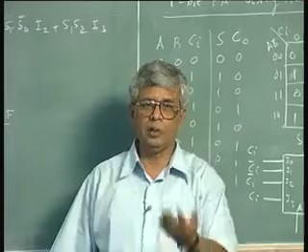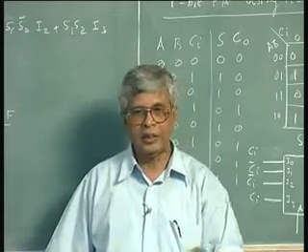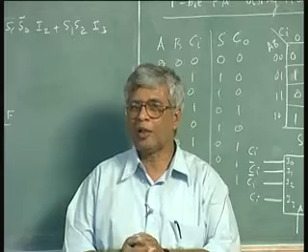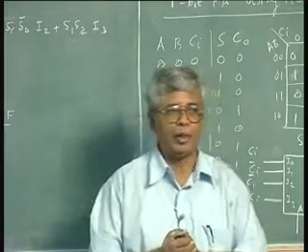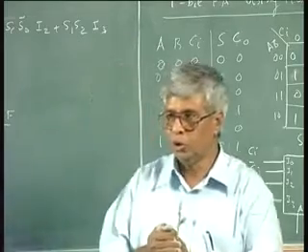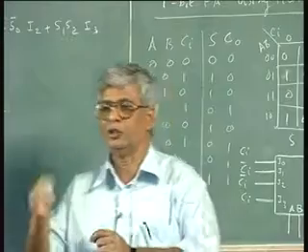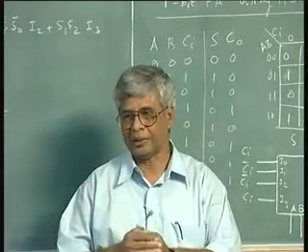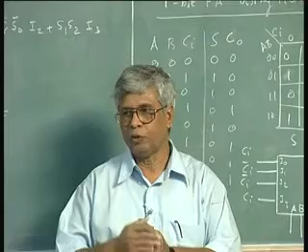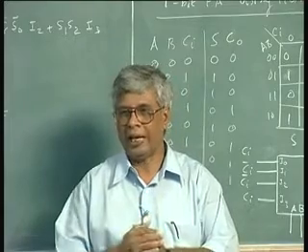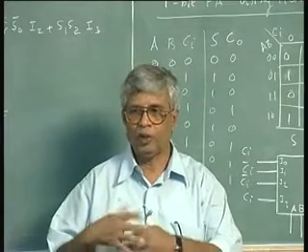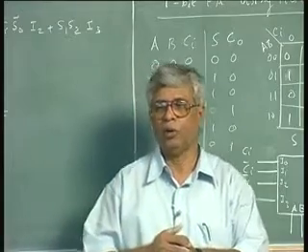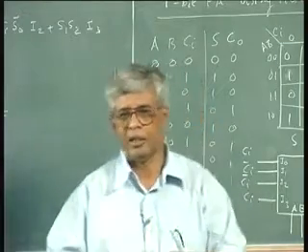So there is no need for me to give you separate homework. What you can do is take any 3-variable Karnaugh map reduction or 4-variable Karnaugh map reduction and try to map them into muxes. First using 4-to-1 muxes, and if necessary sometimes you can use 8-to-1 muxes. Of course we will do some more examples in the class, but there is no need for you to wait for me to give a formal homework assignment sheet.